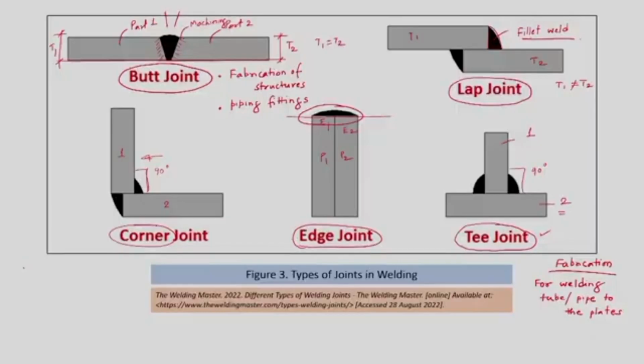So I will just write over here: the rate of travel, rate of deposition, and heat input are controlling the quality of weld.